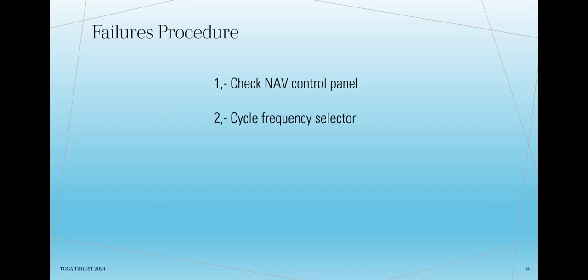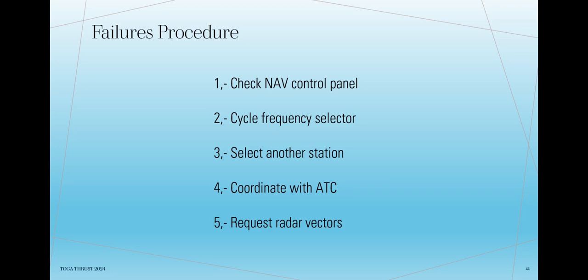Failure procedure. Check NAV control panel. Cycle frequency selector. Select another station. Coordinate with ATC. Request radar vectors.